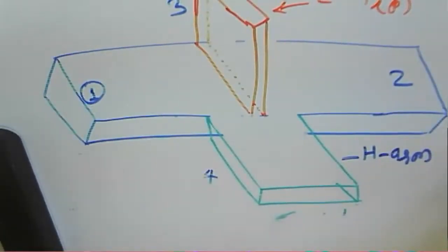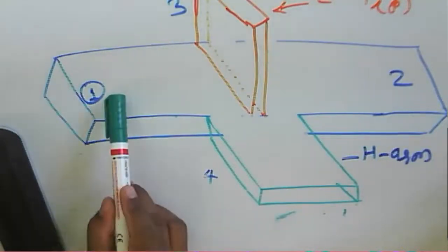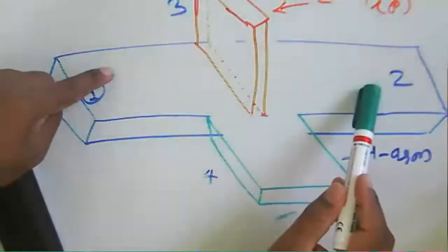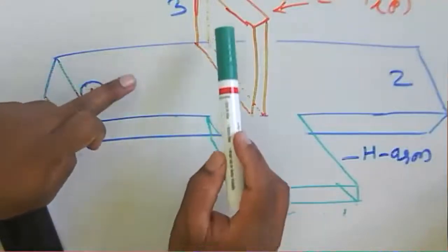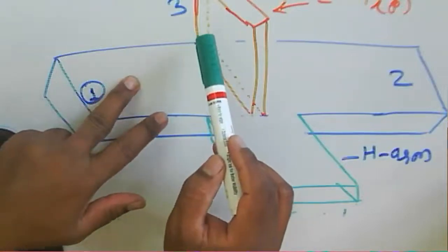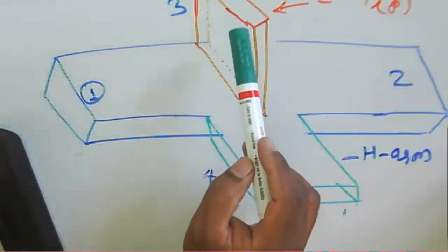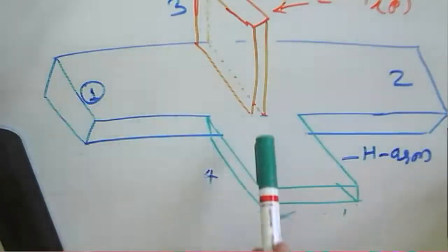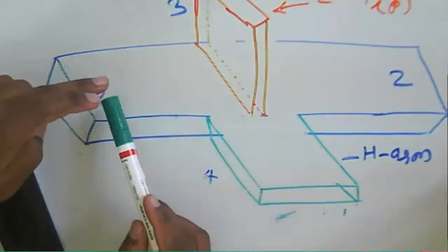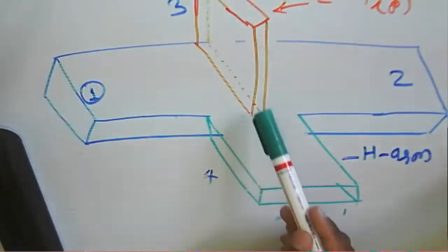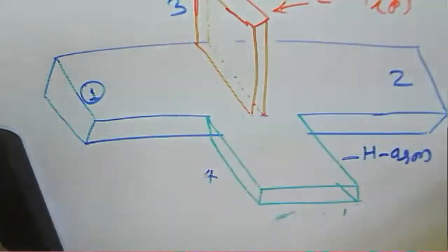If we provide the same signal to port 1 and port 2 here, then what happens? At this E plane, because we say that the E arm is the difference arm, the output at this E arm is the difference between port 1 and port 2. Similarly, the H arm gives the sum: a summation takes place at one arm and a difference takes place at the other arm. So what is the S matrix for this magic T?